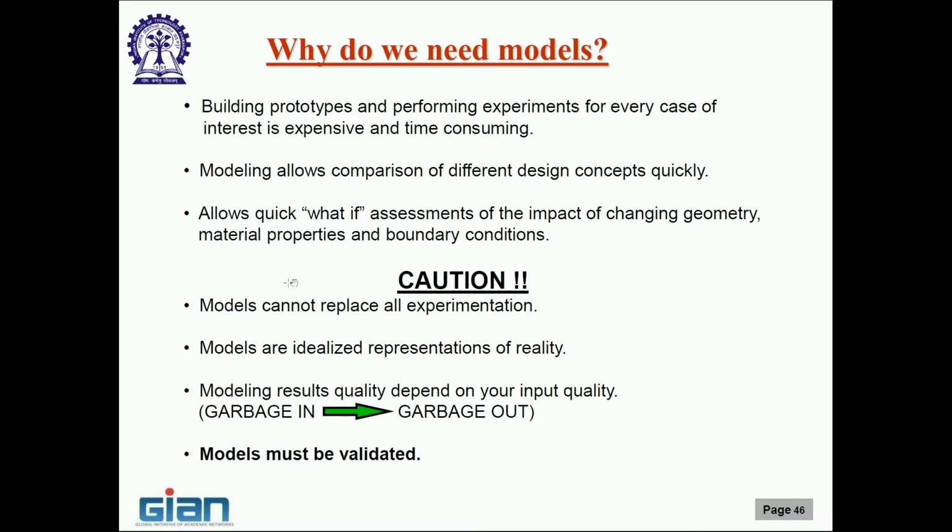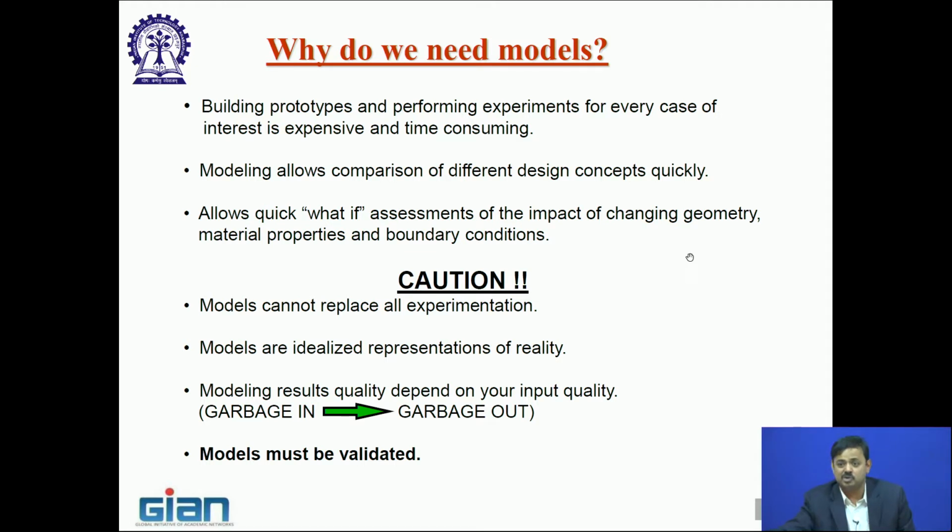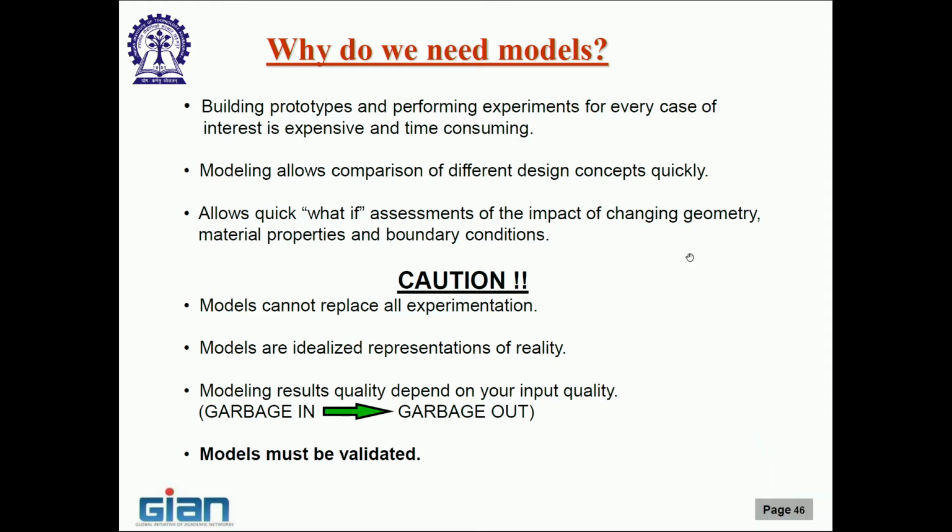Okay. So, it allows for quick what-if assessments. What if I did this? What if I put a vent over here? Is it going to help solve my problem? Okay, try it out in the model, see if it works, then only I am going to put it, because otherwise, for example, in the laptop skin, if I have to put a vent, it calls for a complete tooling change. It is very expensive. So, I have to get it right the first time.